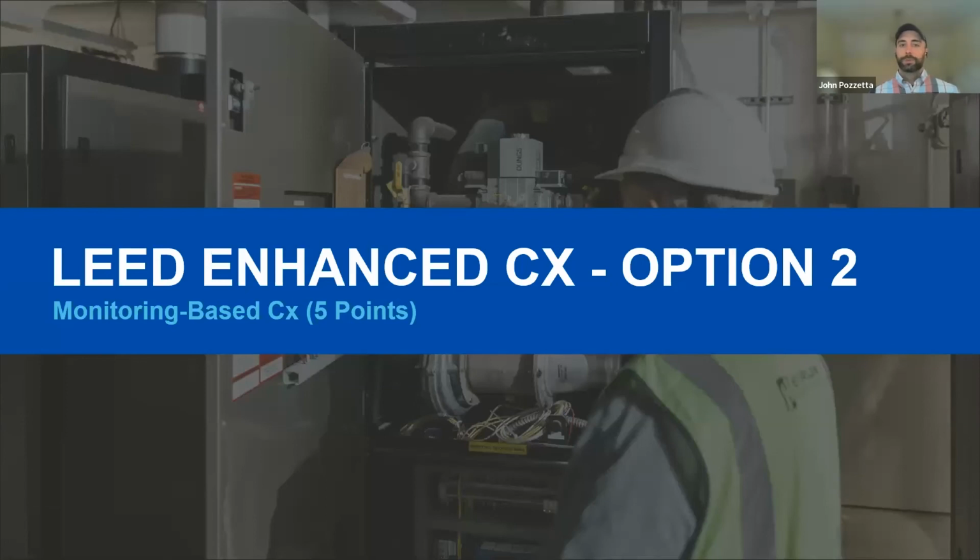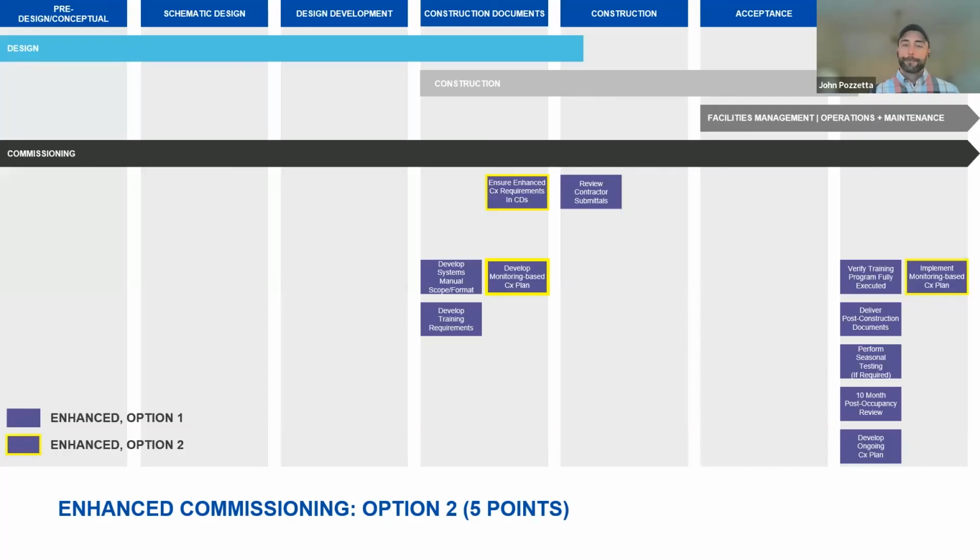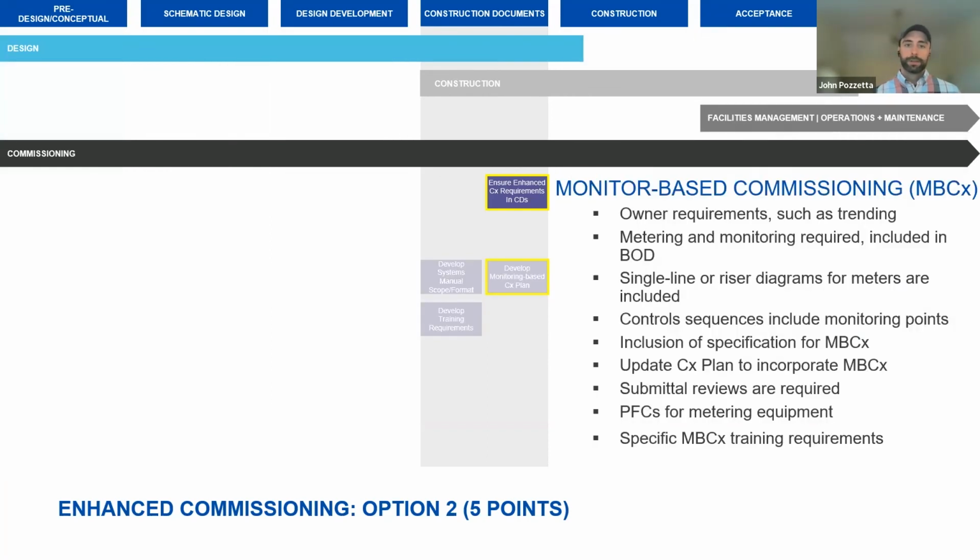So we just discussed option 1. Option 2, enhanced commissioning, is monitoring-based commissioning. That's 5 points. Option 2 requires that you have already addressed option 1, enhanced commissioning. So we can't just selectively choose monitoring-based commissioning. This requires that we perform your standard enhanced commissioning to achieve it. But it is 5 points. And if the metering and monitoring is in place, it's definitely worth pursuing.